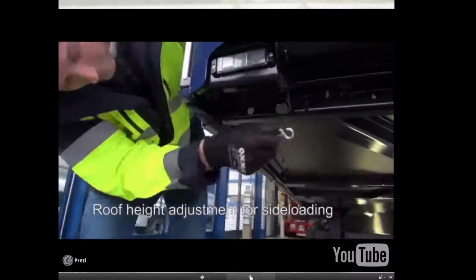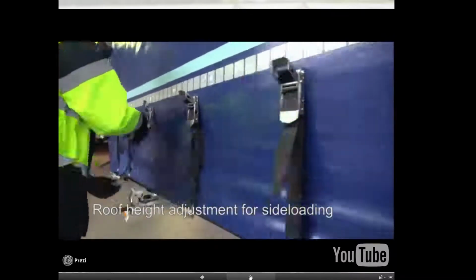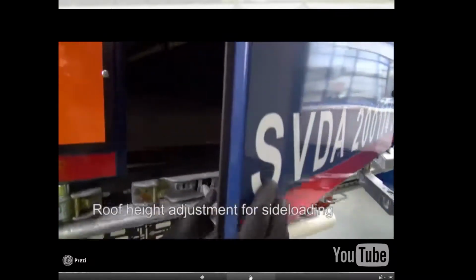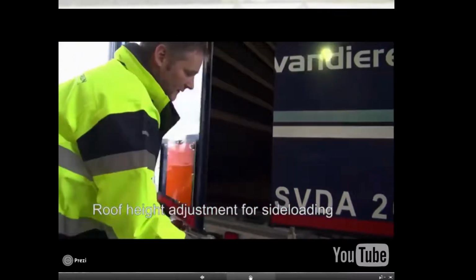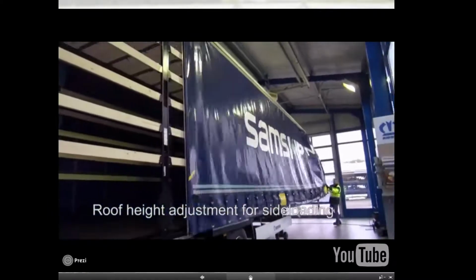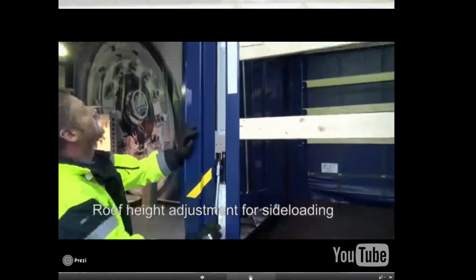The loading of the trailer can be done from the side up to 3 meters. Right now you see how the roof can be lifted for optimal loading from the side. The curtain needs to be unsecured and the doors on the back side need to be opened. If we would lift the roof without opening the doors, this would damage the doors due to the fact that the door and the roof are coupled. The roof can be lifted on each side of the trailer.